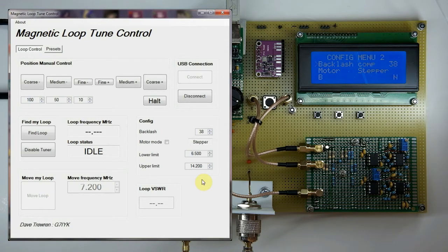Generally speaking, most people tend to use a motor with some sort of reduction gearbox. My stepper motor's got a 27:1 planetary gearbox bolted on the back of it. I've seen guys using DC motors with worm gear type reduction gearboxes, giving them a few RPM. So the problem with a gearbox, unless you spend absolutely crazy money on one, is that